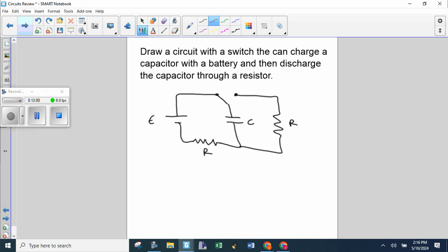Right? So the second resistor current is the battery now. Their placement matters in charging up the capacitor because remember that your time constant is RC. I made them the same in this picture because RC affects how quickly it charges up and how quickly it discharges, but that's all that it would affect. And the location of the resistor, whether it be here or down at the bottom, doesn't matter because there's not really a sequence to it. It all happens simultaneously. We use the flow analogy, but it's not really flowing. It all happens at the same time.